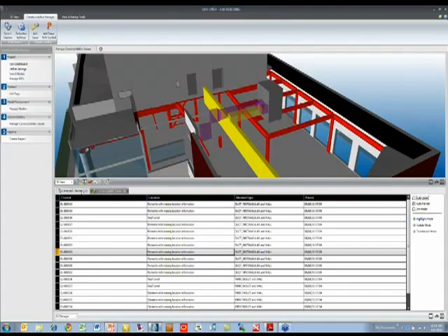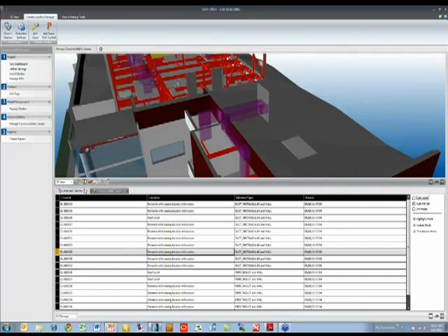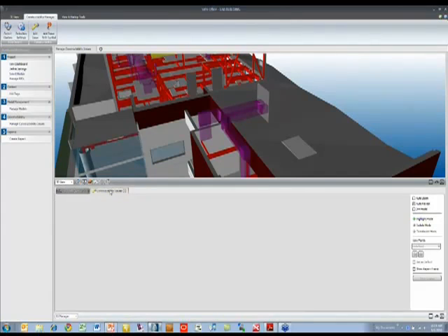At the moment, you see that there are 18 clashes that we have detected, and we have 6 constructability issues. The way that we promote it is just to right-click the line and say mark as constructability issue, and then you'll see that this dives down to 17, and we have an increase to 7 in the constructability issues tab. So what we're doing is promoting this item, this problem that we found, and now able to add more detail to it in the constructability review.